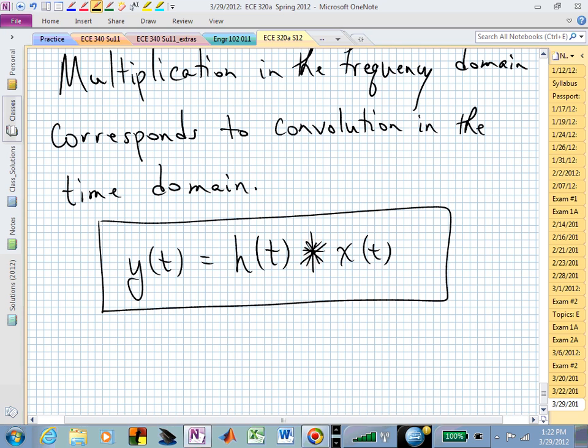So if you had a signal in the time domain and you wanted to perform a windowing operation, to examine that signal between, let's say, 0 seconds and 20 seconds and throw everything else away, that's like multiplying that waveform by a rectangular window function. And so now you would be convolving those two signals in the frequency domain to get the response.